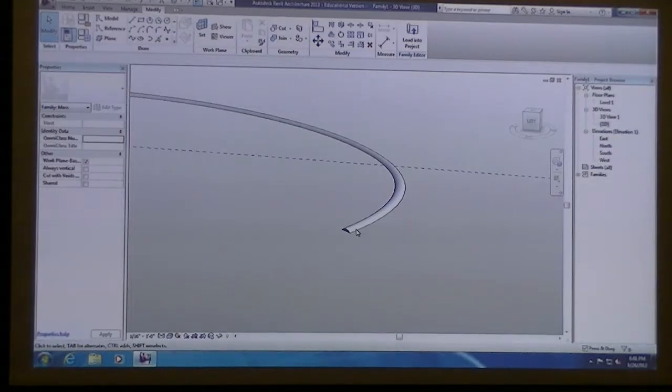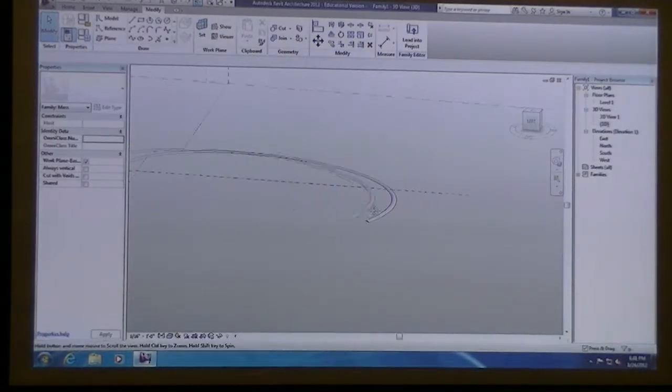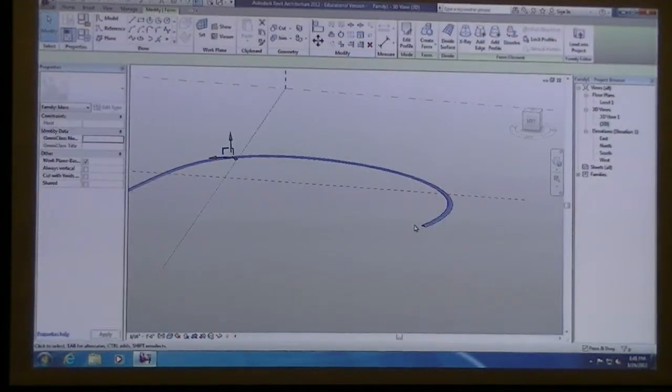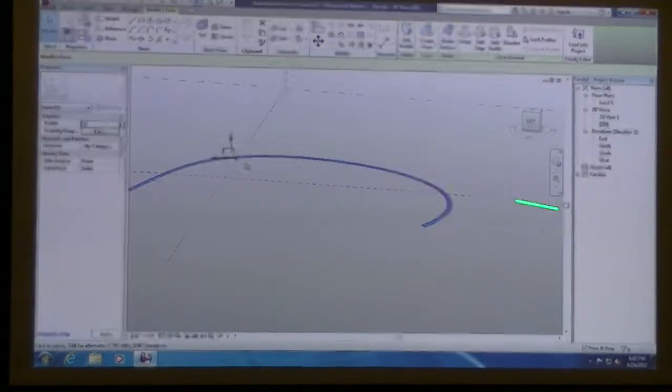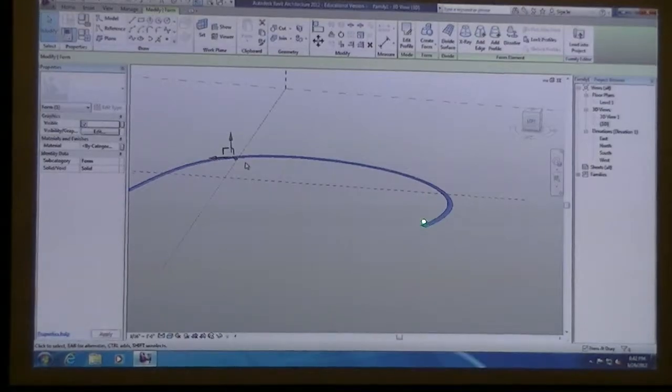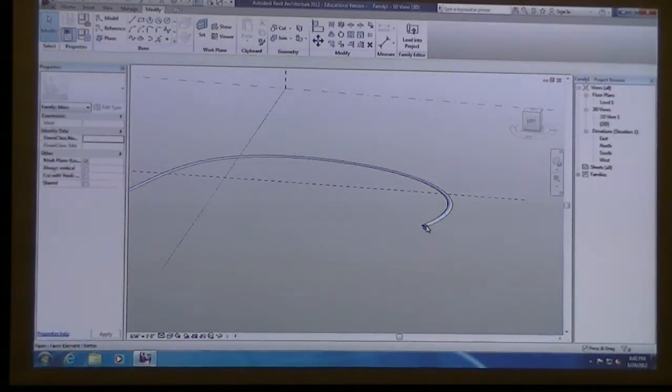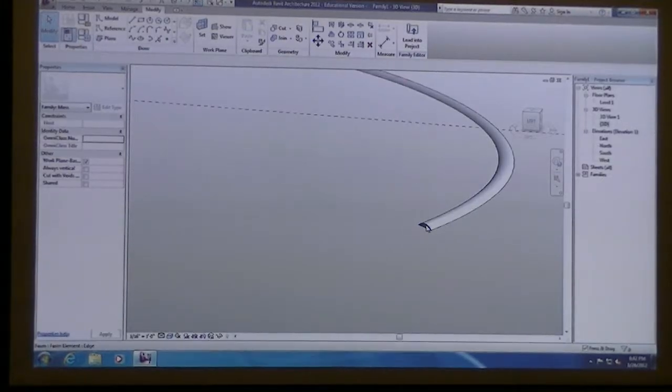So basically with that method, what you'd want to have established is a set of points on this spline that you could actually move. So you probably want to set up those points first, kind of like we've already done in some of these other curves. At least have 4 or 5 points that have some ability to move the dimensions.